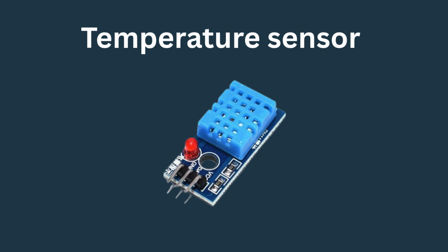The humidity sensor consists of two electrodes with a moisture-holding substrate in between. As humidity changes, the substrate capacitance changes, which is converted to a digital signal. For temperature, the thermistor resistance changes with temperature and is also converted to a digital signal. These digital signals are then transmitted to a microcontroller via a single wire interface.